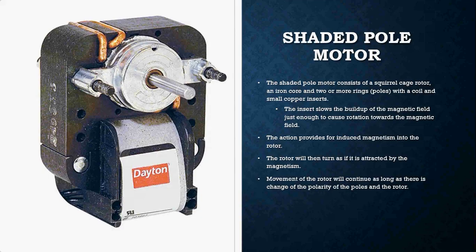So the first motor that we want to get into is the shaded pole motor. Now, the shaded pole motor, in my opinion, is probably the simplest of all motors that are out there. There's really not much to these motors. The shaded pole motor really consists of nothing more than a squirrel cage rotor, an iron core, and two or more rings, better known as poles, with a coil and a small copper insert.